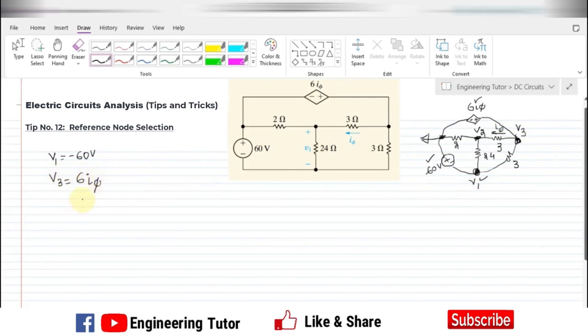Similarly, the value of V3 is also known, and that is 6I5. Here we can see that the value of I5 is the current flowing from V3 to V2 through the resistor 3. So I can write that I5 is the potential difference, V3 minus V2, divided by 3.